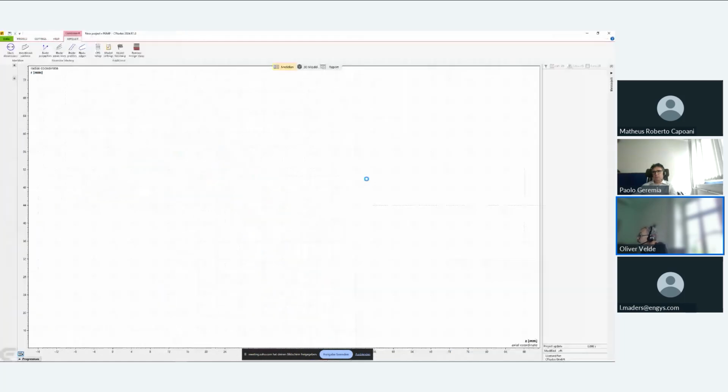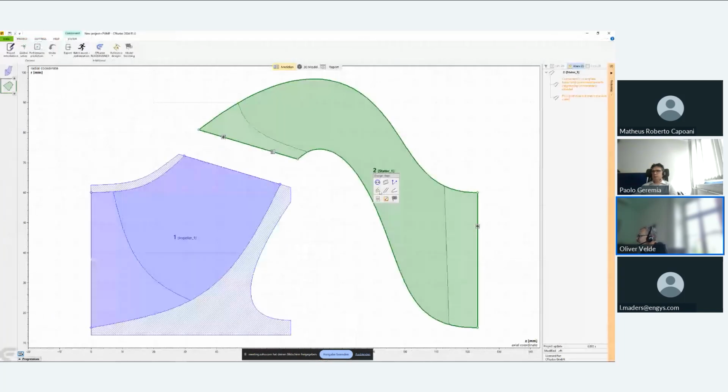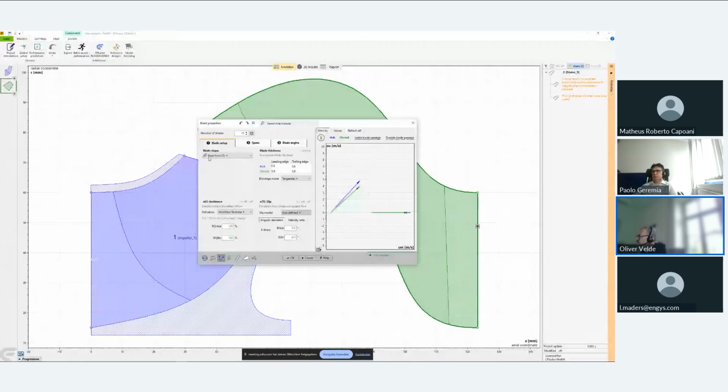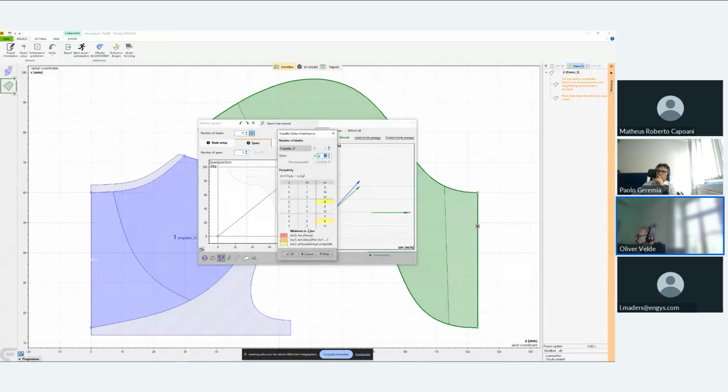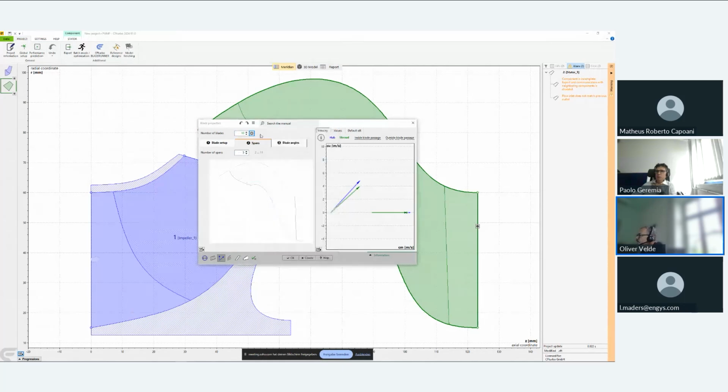Okay, very simple, similar to the impeller. The next design step is to tell what is the general shape of the blade, what is the number of spans I want to use in the design process, what is the number of blades I want to use, and that can also be chosen with respect to, for instance, some interferences that might happen between impeller and stator blades. And to this end, again, the default is given in order to have, for instance, a lower noise level.